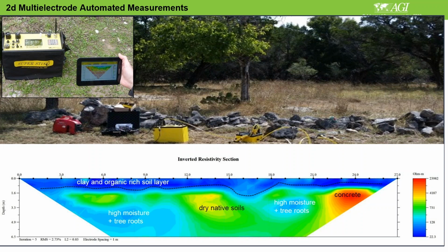Just consider that if you're doing a laboratory measurement, you cannot use that one. Because if you're using maybe 1 inch, or like 3 centimeters or 5 centimeters electrode spacing in the laboratory, in that case you cannot use that 45 centimeter stainless steel electrode I mentioned. You need to use a very, very thin nail in that case.